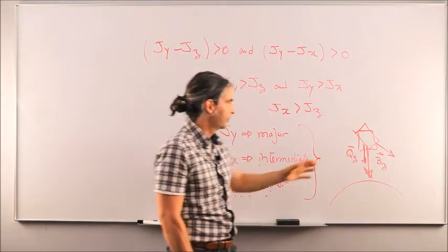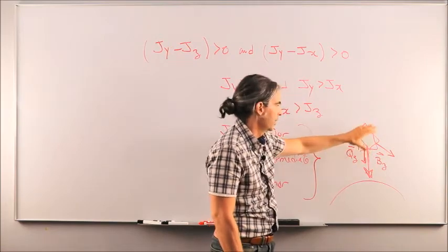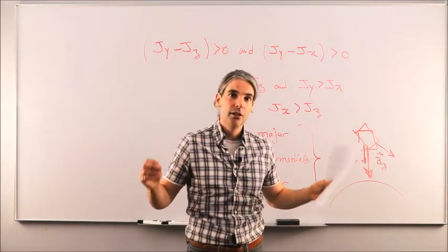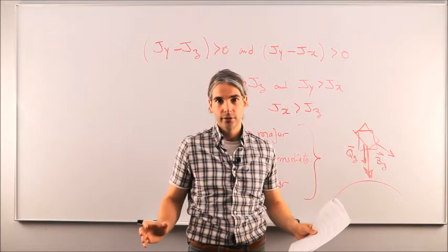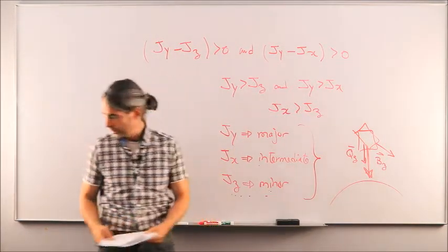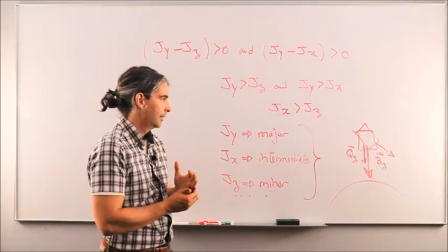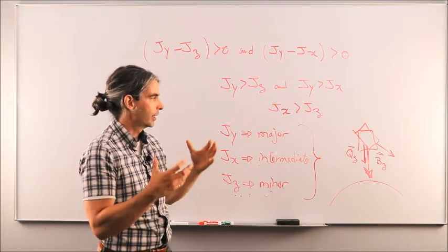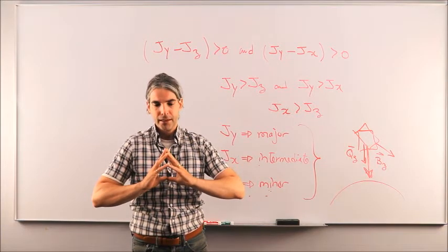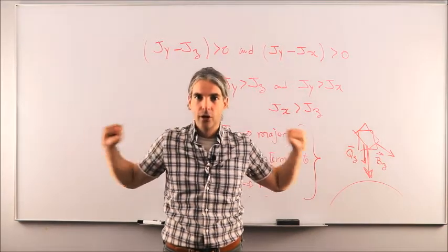So to maximize the efficiency with which the gravity gradient torque restores the spacecraft orientation always in the nadir configuration, well, the trick is simply to maximize the difference of your principal moments of inertia, okay? Because gravity gradient is proportional to the difference in principal moments of inertia. And one way people do that in practice is by putting on their spacecraft large deployable booms, okay? Think of that as rigid rods that get deployed in orbit.